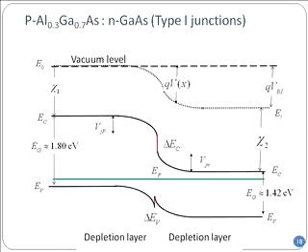Because it is actually p-type for the emitter and n-type for the base. Do you see that the green is again the flat Fermi level, and on the n side, in the gallium arsenide side, the conduction band is very close to the Fermi level, and correspondingly the valence band is very close to the Fermi level.